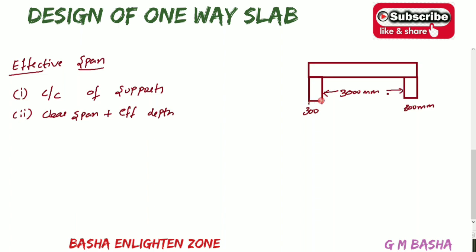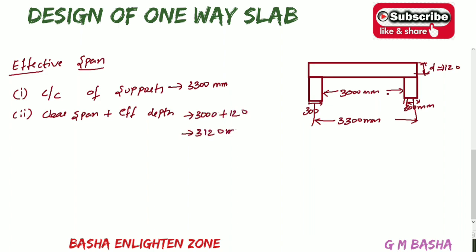The clear span is taken from here to here, and here also from here to here. For center to center of the supports, 150 on each side gives 3300 mm. So the first value is 3300 mm. The second is clear span plus effective depth. Effective depth, from the center of the bar to the top, we already fixed according to the span to depth ratio as 120. So 3000 plus 120 gives 3120 mm.